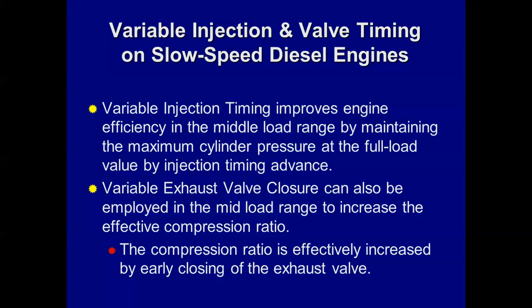So the main thing on this, variable injection timing for heavy fuel oil ships, allows you to adjust the timing of the engine depending on fuel quality to make sure that you get a clean burn and give you the best fuel economy.